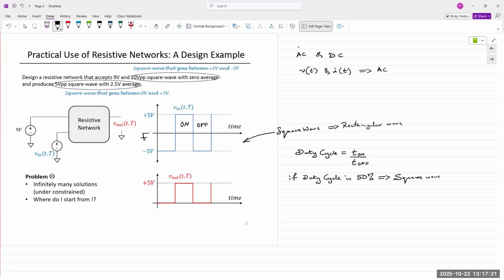Whether it's a sine wave or a square wave, it doesn't matter what kind of waveform you're observing, it will show you the reference. If that reference is at ground, then that waveform is centered exactly above and below that reference point, meaning it's running in the center.